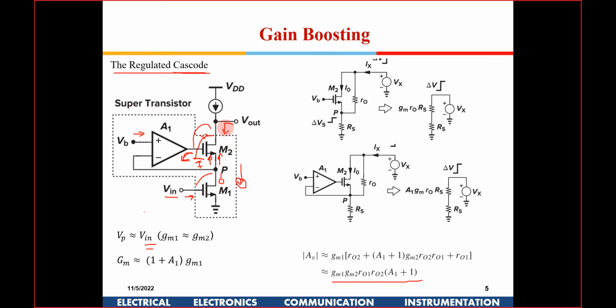It has to flow out here. Whereas if you have a Miller capacitance here, your small signal will start getting shorted out at this particular node itself, at the gate itself. You have a large capacitance. So this capacitance out here doesn't really affect your gain. When you are looking from here, it is just 1 by GM. So that doesn't come in the small signal path actually.